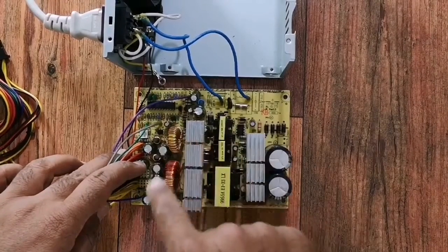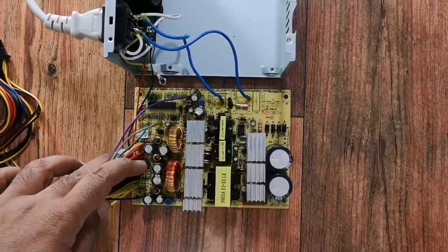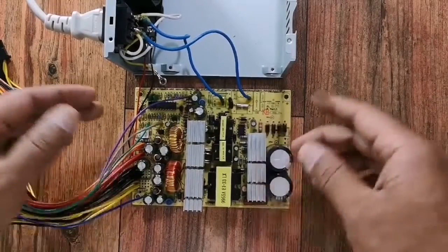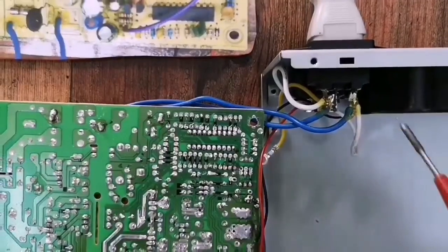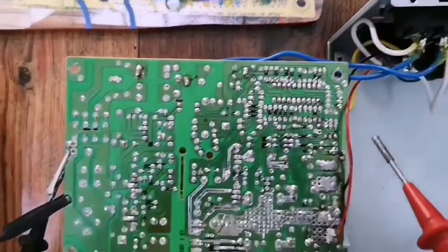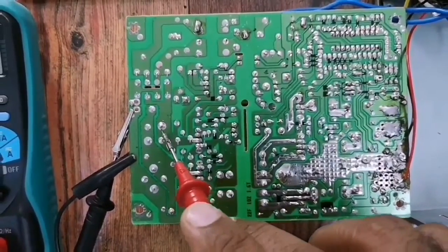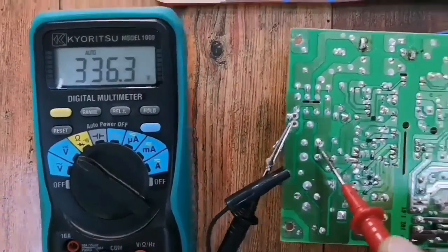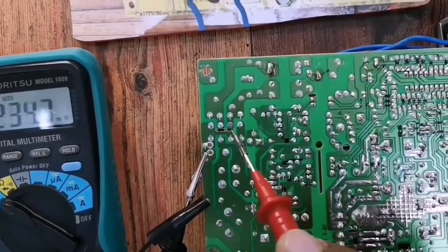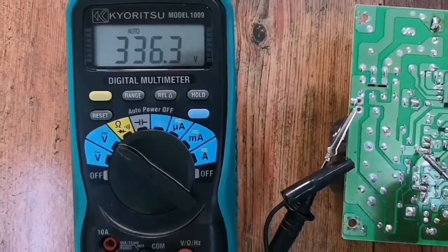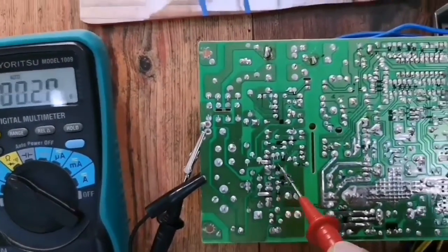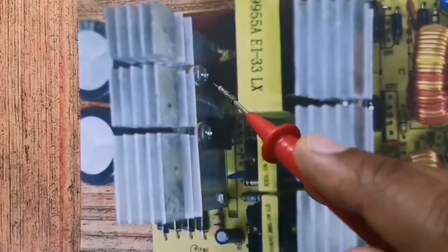Try to recall the location of components, as during the test I'll put the board upside down, and I will use the picture of the top side to show. The power is applied, and here we get the DC supply normal after rectification and smoothing, and it is reaching to the collector of switching transistor. I have checked these 2 transistors during power off. They are okay.